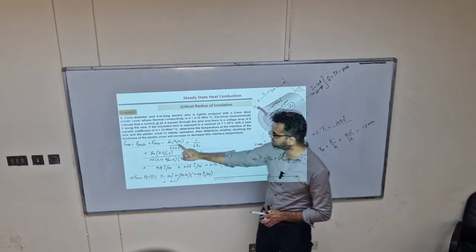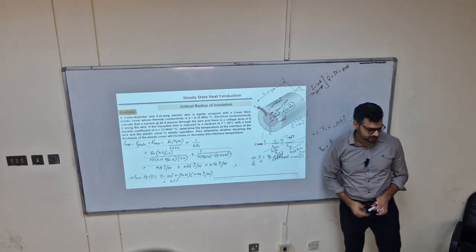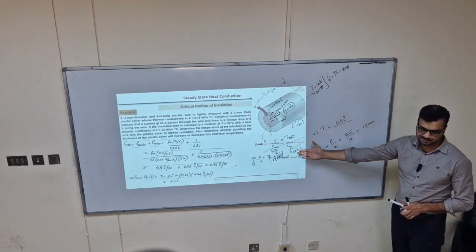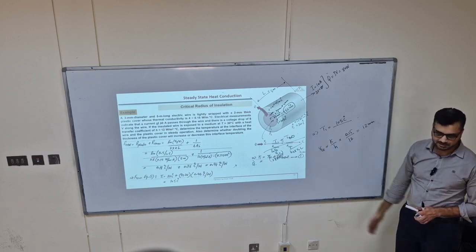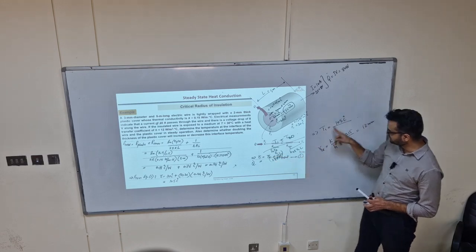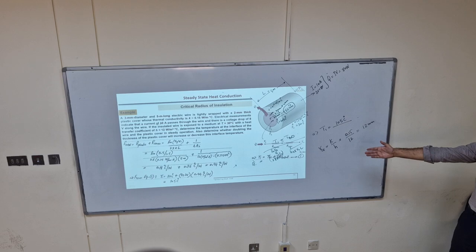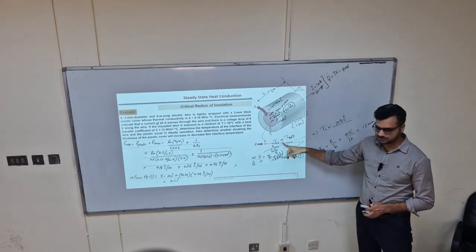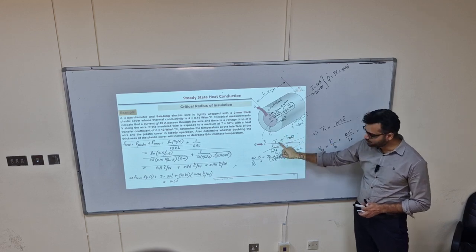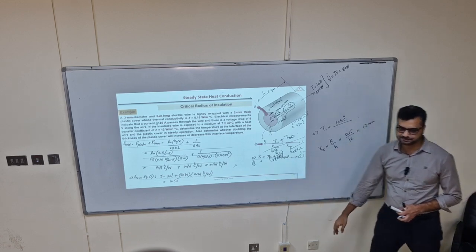Determine whether doubling the thickness of plastic cover will increase or decrease this interface temperature. So can we do it mathematically? Yeah, you have this mathematical equation. That is the formula. Put Q as 80 watts, solve it again, and you will see T1 will drop. Q is increased, but Q is fixed. So where will this effect go? Somewhere here. T infinity is fixed. So it means T1 has to drop because you are increasing R2, keeping Q fixed.